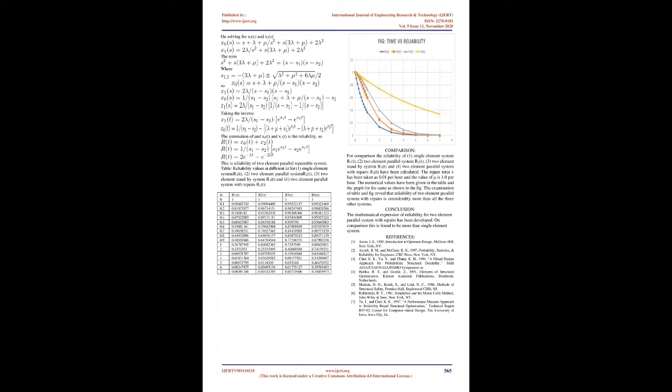C. Mean time to system failure. This is used to evaluate the expected average working life of individual components and systems, which may be of maintained or non-maintained type. This has three subdivisions as follows. A. MTBF, mean time between failures. This is the average life of a component. It is obtained by testing many identical items, like the life of an electric bulb, a bearing, etc.